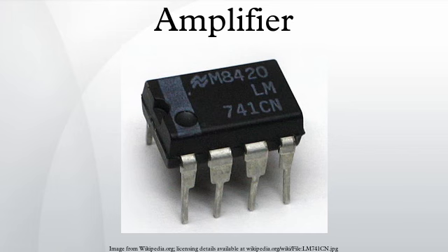A linear amplifier responds to different frequency components independently, and does not generate harmonic distortion or intermodulation distortion. No amplifier can provide perfect linearity. A nonlinear amplifier generates significant distortion and so changes the harmonic content. There are situations where this is useful. Amplifier circuits intentionally providing a nonlinear transfer function include a device like a silicon-controlled rectifier or a transistor used as a switch, which may be employed to turn either fully on or off a load such as a lamp based on a threshold in a continuously variable input.